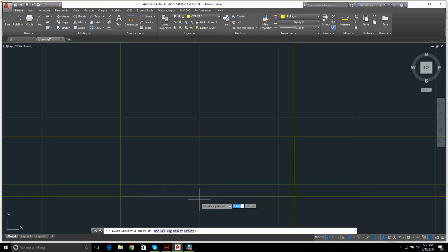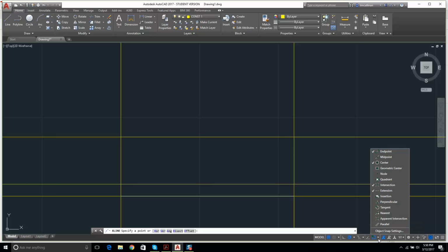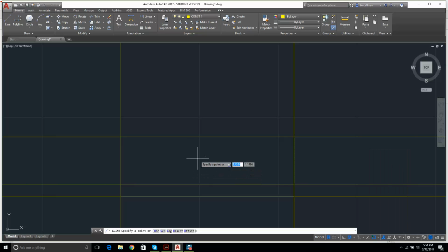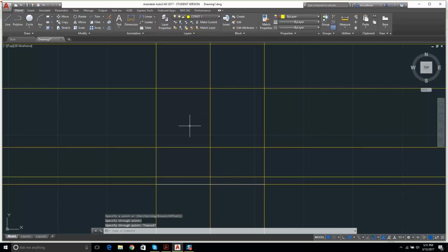And notice it would be very, very nice. It seems to snap at each endpoint. It would be nice if it could snap right in the center. How do I do that? That's called the midpoint. If I check this arrow and I select this midpoint and I go back again, I want that to lock in like it does there. And now I have that center point.